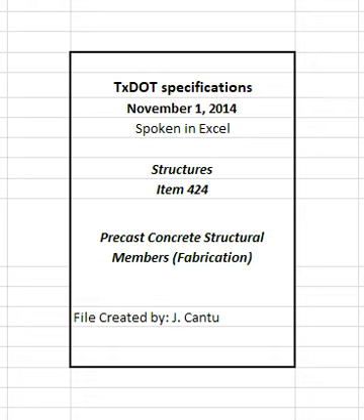4.2.7.3 Membrane curing. Liquid membrane forming curing compound is a moisture retention covering that is applied as a liquid. It is only permitted as noted in Section 424.4.2.7, Curing of concrete. Use Type 1D or Type 2 membrane curing compound in accordance with DMS 4650, Hydraulic Cement Concrete Curing Materials and Evaporation Retardants.